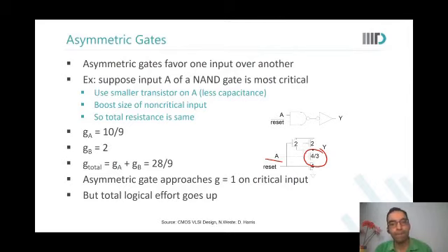And this critical thing was not clear, like the path of A. Critical path over here would mean the path which has the largest delay. So A was coming from a path which had the largest delay. A was coming last, so I wanted to put A closer to the output. That I already did. Now I want to improve performance further. So what I did was I reduced the load on A also, so that A can arrive a little faster.